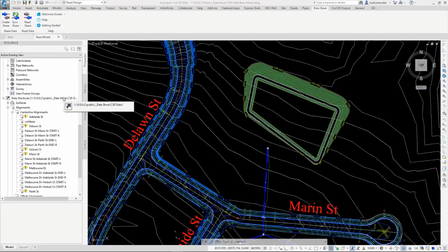Thanks, Todd. No problem. So it took me a bit to bust it. Not only did I rename the project folder for the Civil 3D data shortcuts, I also shifted the source location for one of the files just to break fundamentally the connection. I'd love to say that data shortcuts are amazing. They just keep finding and fixing themselves automatically. That is super. But you've busted it. Got to remember the connection is to the drawing, not the shortcut. The shortcut's just to facilitate the connection. So we had to break the location of the drawings relative to each other to force the break.